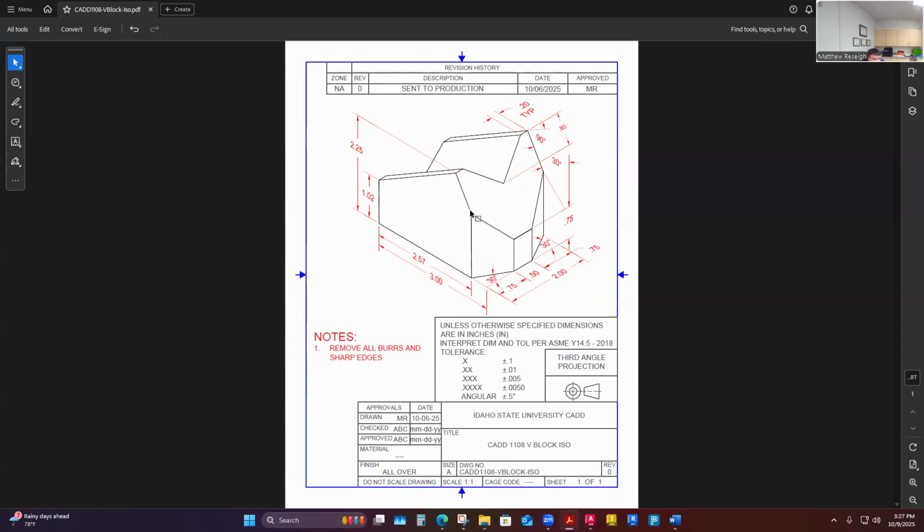All of this material in my right side view is going to be foreshortened. Not this, but these are. This I would pick up as the true length. I would see that 0.2 dimension in the right side view. This would be foreshortened because I'm on this view plane. So what I'm able to identify, and you have to put your mind through that work maybe before you even start drawing, is that I get pretty good data on the front view. I get a lot of true lengths there. I get some, but not great.